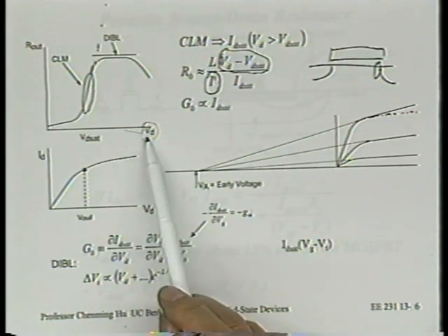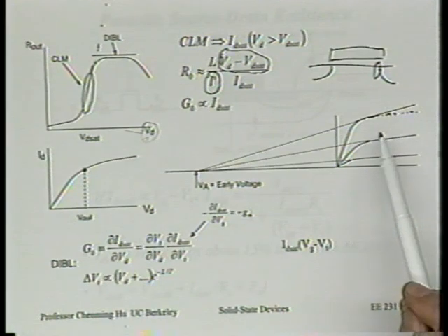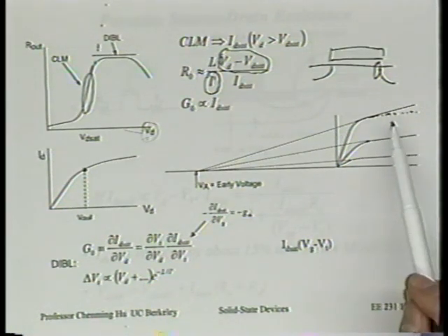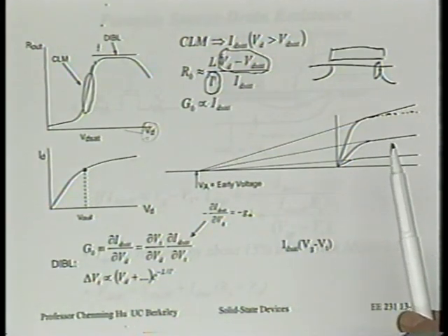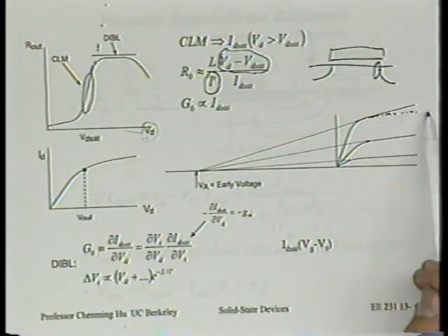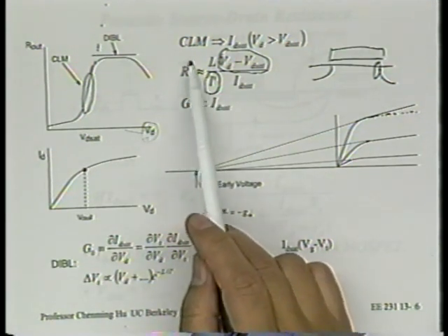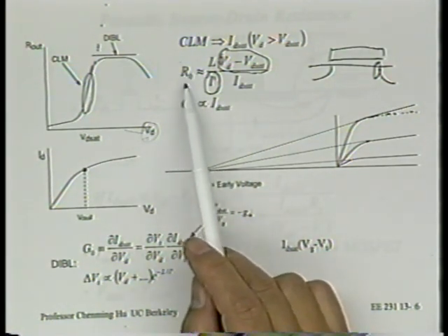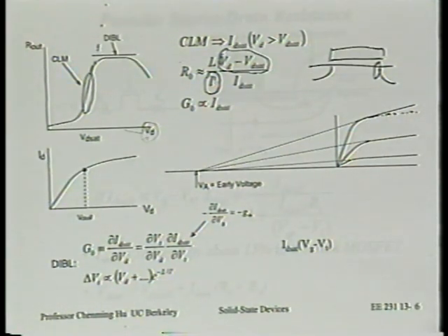Is that right? That means it's almost a straight line. And for those of you that have done circuit design, look at this carefully, it's a pretty good approximation. It's pretty much a straight line. That is, slope does not change with VD, whereas the Chenming's modulation mechanism would predict that slope should constantly change with VD, or decrease with increasing VD.